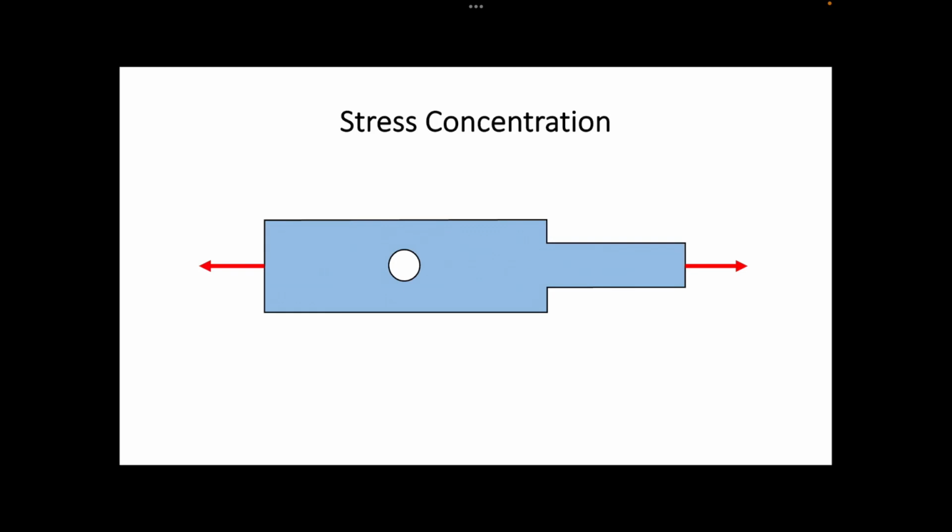To be specific, let us consider the bar on the screen, which is subjected to an axial tension load. To visualize the stress concentration, let me introduce to you a technique that engineers usually use, which is called the force lines method. It is based on the similarities between the flow of forces and the flow of water.